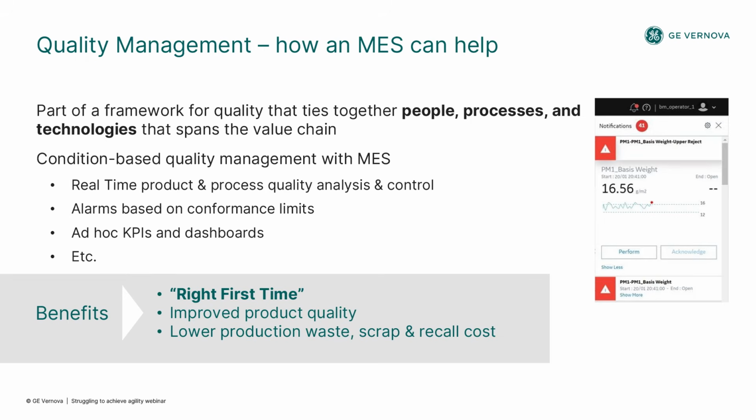So you can do this on not just going above the reject limit, but bouncing around in the warning limit. And again, understanding, so, hey, I'm trending outside of my warning, therefore I might have a problem coming up, and the ability to get that fixed before you go out of reject, while you're still bouncing around in the warning area. Really improves your quality, right? So reduces the waste because you can address an issue much faster and much sooner than if you didn't have this information.